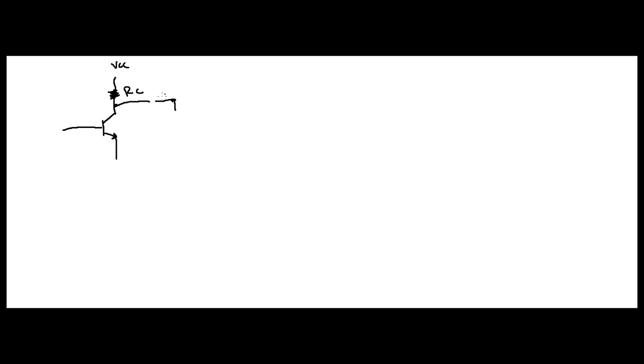Remember, you have, let me draw it in here for you. So your actual circuit is going to have a capacitor in there, right? But remember, we're talking high frequency. So when you're talking high frequency, that capacitor acts like a short, doesn't it? It's just like what we did on the input. So let's just draw that straight through, right? And then we come down here.